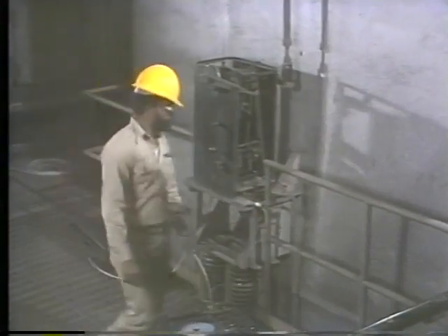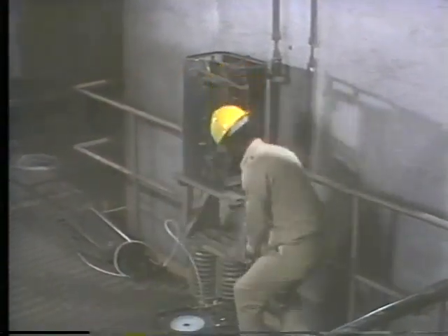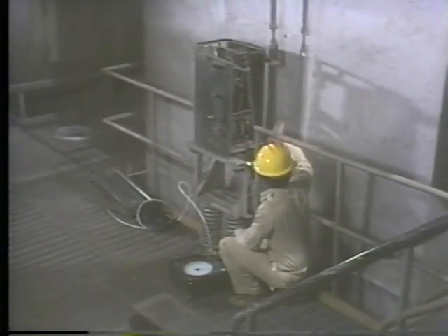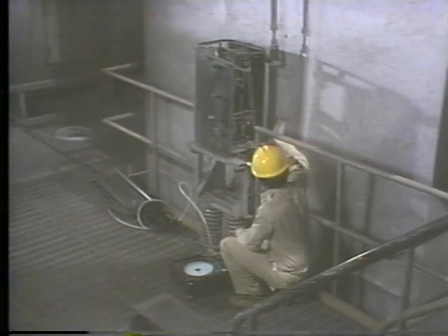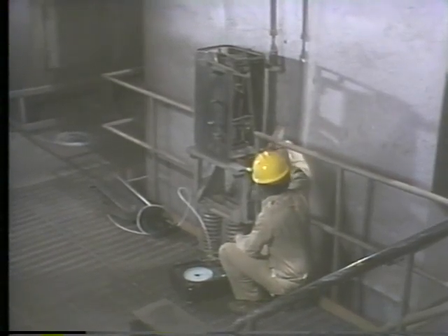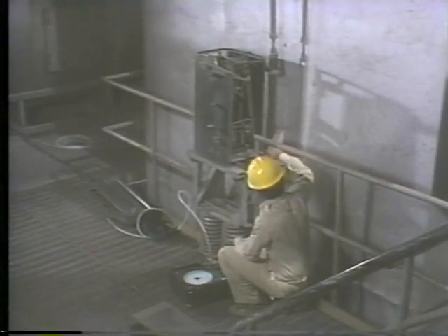Once the manual loader is properly connected, the supply air can be opened up to allow air to flow to the instrument. At this point, if the regulator wasn't turned off, the supply air would flow through it to the positioner, where a sudden surge of air pressure could damage the input bellows.